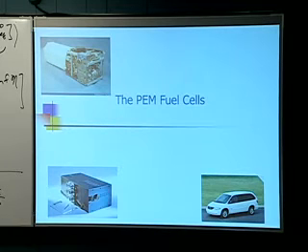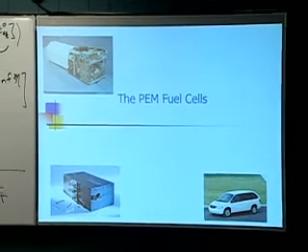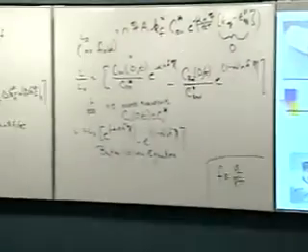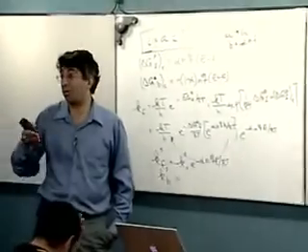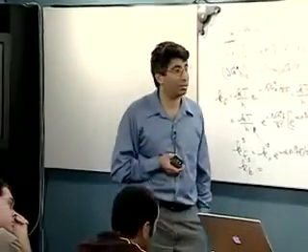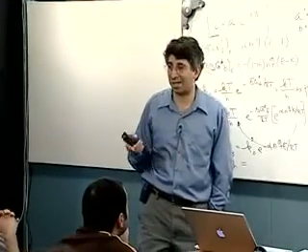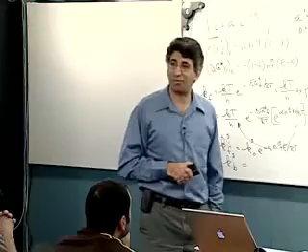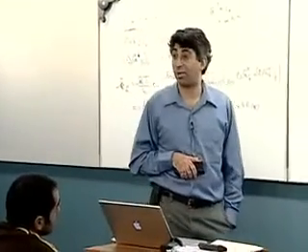You can take those gas cylinders up to higher pressures, say 5,000 psi. But of course, to do that, you have to make the steel thicker. And we've probably all lugged a tank down the hall once. We know it's already heavy enough. When you get to 5,000 psi, you essentially double the mass of the tank, then you're paying an awful lot of energy cost for carrying around that tank.